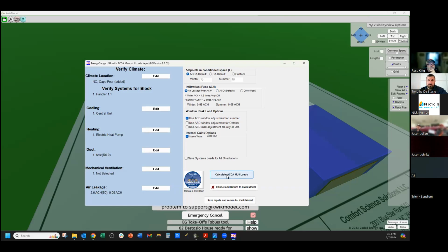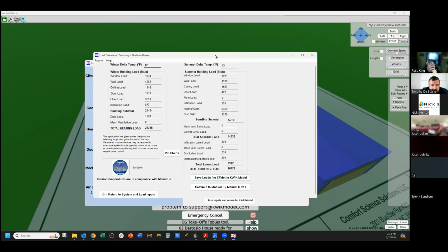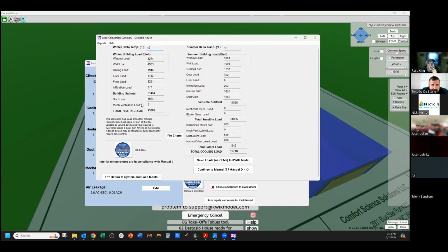Then you click this magic Calculate Manual J button here, and it will do your load calcs for you. And there they are. Your winter is 23,388, the summer sensible is 14,000, and the latent is 1,900, for a total of close to 17,000.